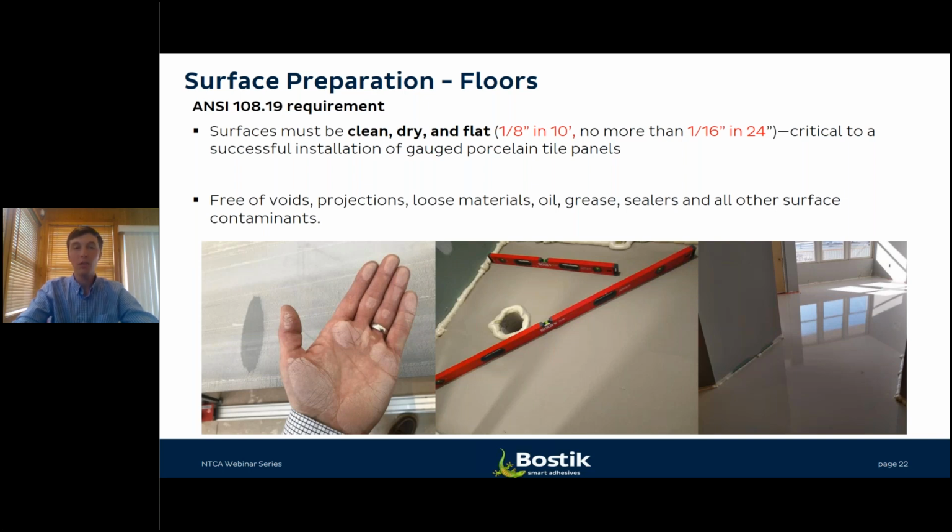So when I say clean, if you look at the picture of the hand on the bottom left, this hand was just dragged lightly over the face of a gauged porcelain tile seconds before installation, and you can see there's a significant amount of either dust from the job site or engobe or kiln release left over from the manufacturing process on the face of the panel. So this is part of that clean that has to be taken care of on the panel side, as well as on the substrate side.